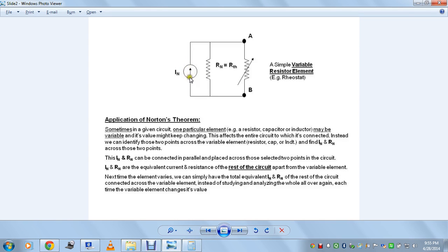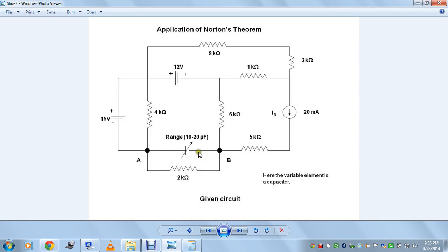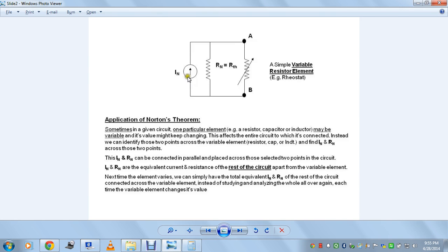current source. The computation of the current source is nothing but finding the current flowing through the variable element here. So in order to find that, we have to short this element using a simple wire and see how much current it flows. You can have an actual piece of a circuit, a printed circuit board, and connect all the resistances in the particular arrangement here and provide such voltage sources and current sources and test for the value by shorting this element. You just find what the current would be flowing through this particular wire if it is shorted between the 2 points A and B. That is what would be the current source.